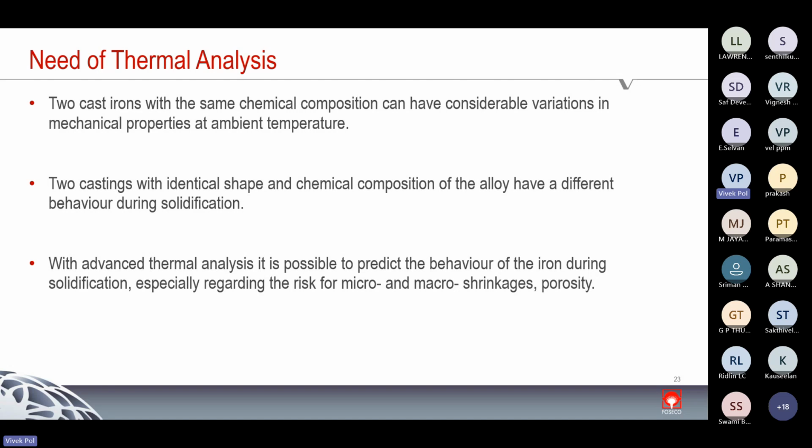Because the chemical composition, which the spectrometer tells us, the spectrometer has no capability to understand the metal nucleation level. It will show how much carbon and silicon, but what the metal nucleation level is, the spectrometer cannot tell us. And for the same chemical composition, nucleation level may vary because of different melting practices.